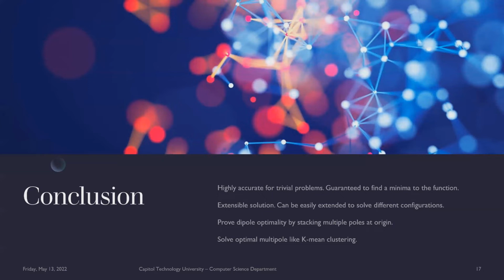It would also be possible to extend this model to solve for positions and magnitudes of a multipole model where the dipoles are not located at the origin. This could be useful for trying to understand the magnetic composition of the article under test. It would also provide the benefit of positioning the onboard magnetometers where they will be subjected to the least amount of magnetic noise. This knowledge could be useful for any other magnetically sensitive science instruments on board the satellites as well.